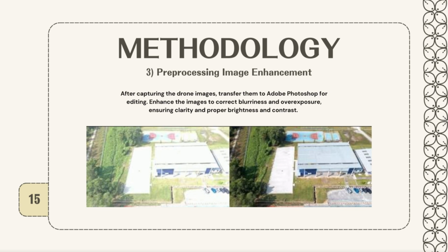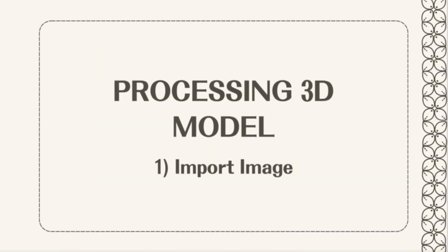After capturing the drone images, transfer them to Adobe Photoshop for editing. This process is to enhance the images to correct blurriness and overexposure, ensuring clarity and proper brightness and contrast. After all of the images have been enhanced, come with me to process the 3D model in Pix4D Mapper. Be sure to follow all the steps.